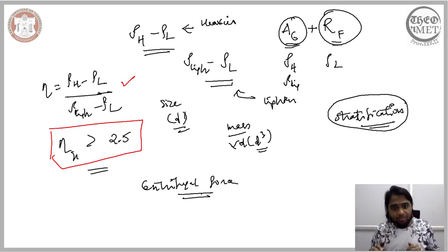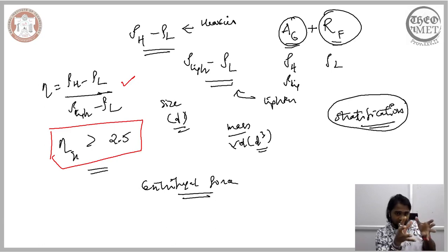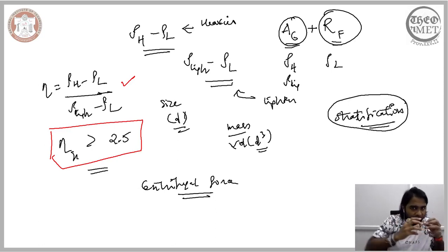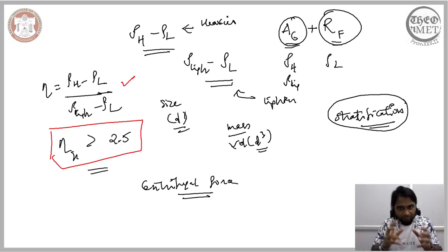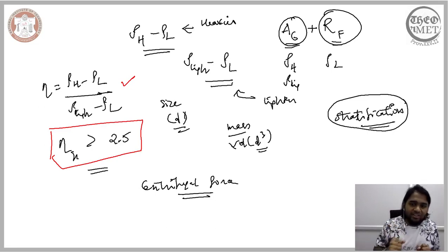in order to enhance their movement, an additional accelerating force is included, and that force is often the centrifugal force. So essentially, even though there is a limitation associated with this rather straightforward expression for the efficiency, even though this expression does not consider the influence of the size of the particles on their movement in a suspended medium, in order to ensure that these small particles also move similar to the large particles, an additional accelerating force is introduced, and often that is a centrifugal force.